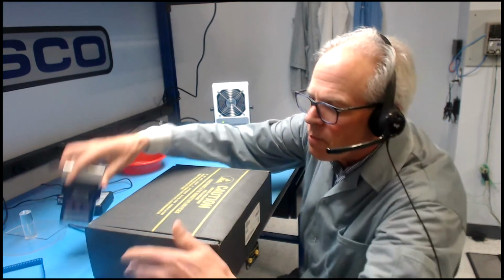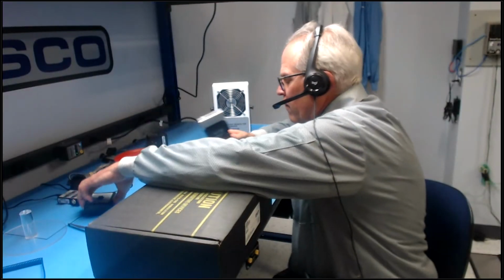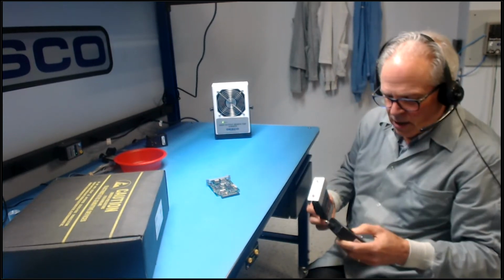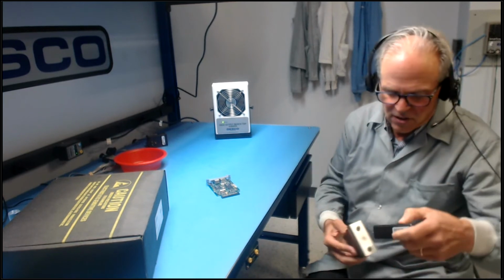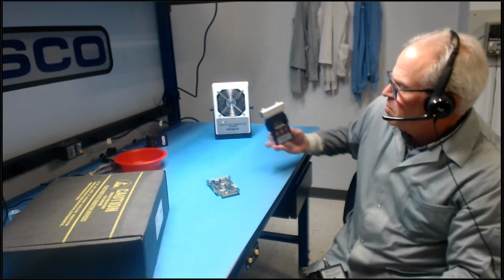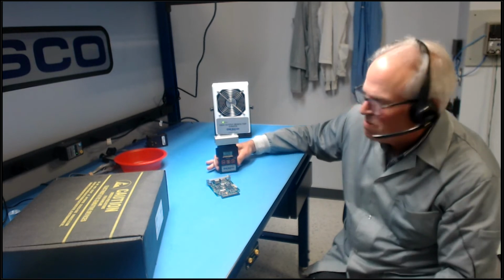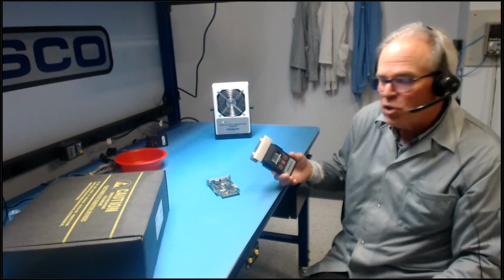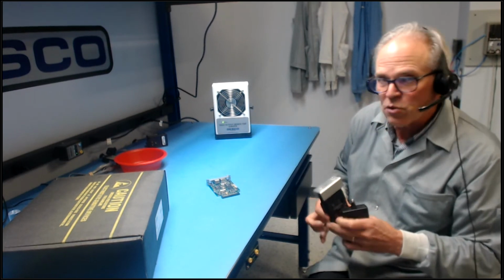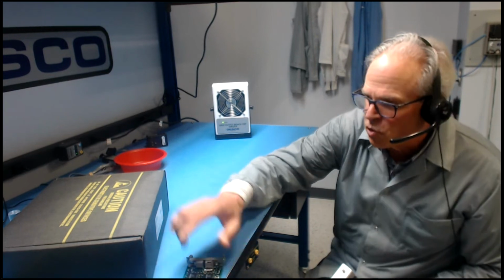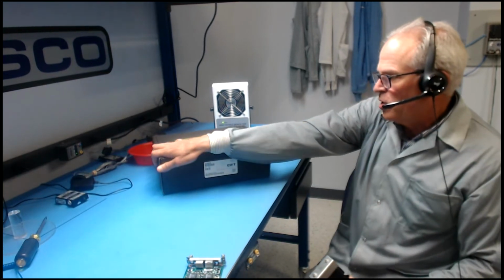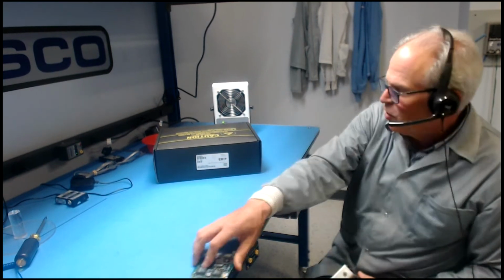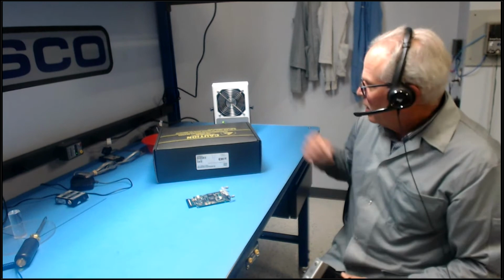Okay, so if this is the target area right here, and let's say it's 6 seconds. I'm going to put the charge on there, 2, 3, it took like 2 seconds. So if you're looking for 6 and it takes 2, that means the ionizer is working well. But sometimes we see situations where there's a lot of things on the bench and people think, well, the ionizer is going to work no matter what. So you have something on the bench blocking the airflow.